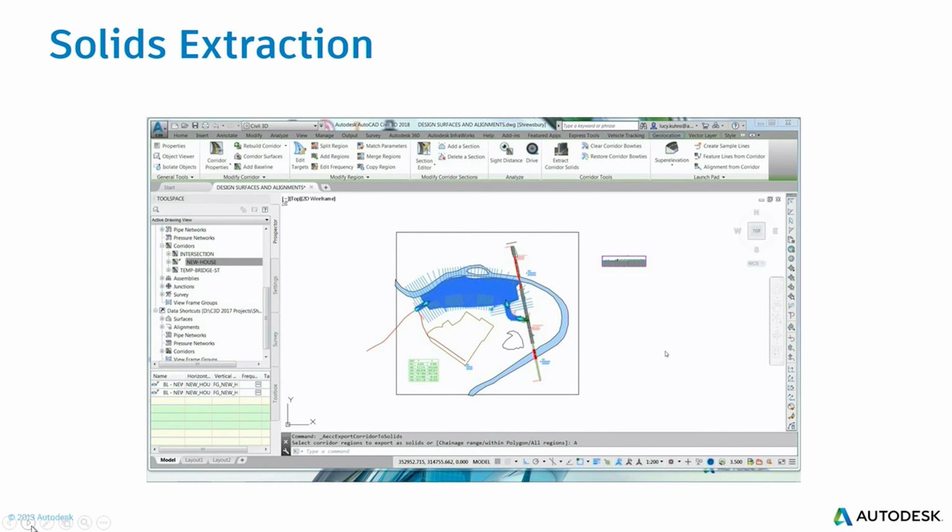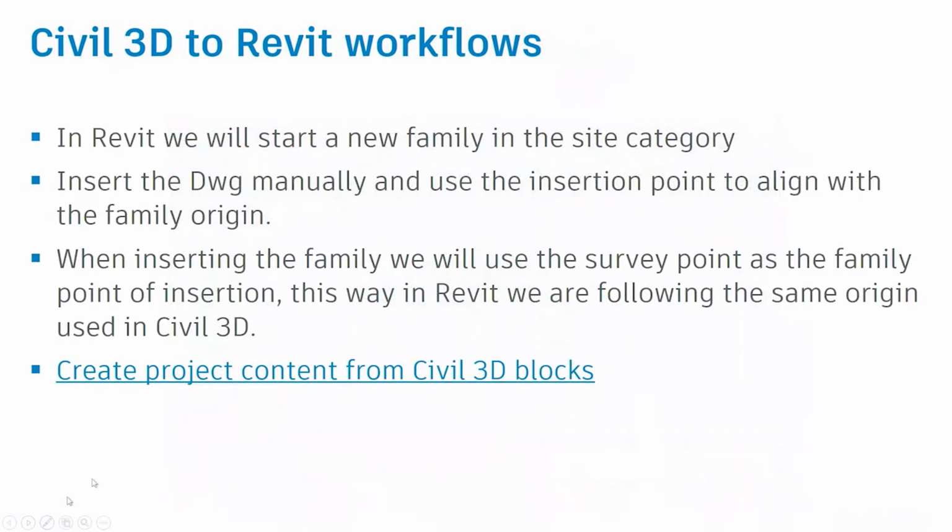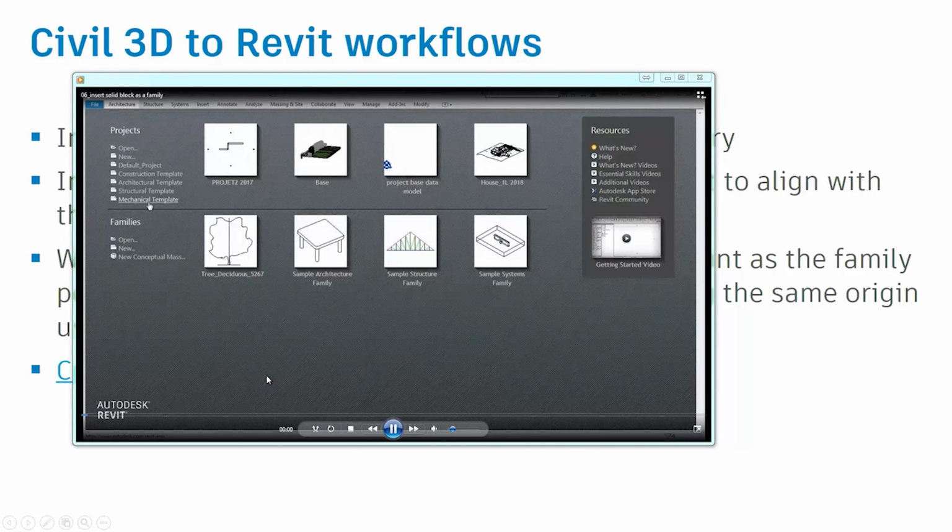So why do we look for this process to do it this way? As probably most of you know, if you link a Civil 3D file with lines or surfaces, you cannot cut it. So in a section you don't see the object, it is not cut. On the other hand, if we link it once and we have repeated objects, for instance light poles or components from sewage systems, sometimes we need to repeat them. It doesn't mean that we want to place it once.